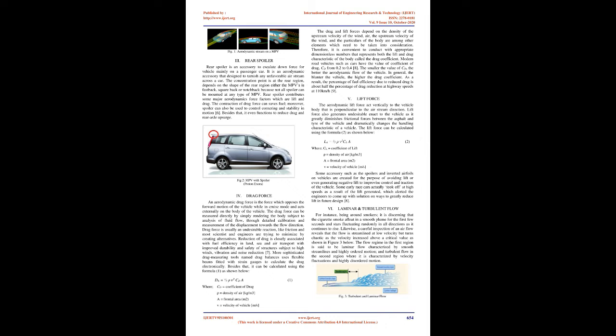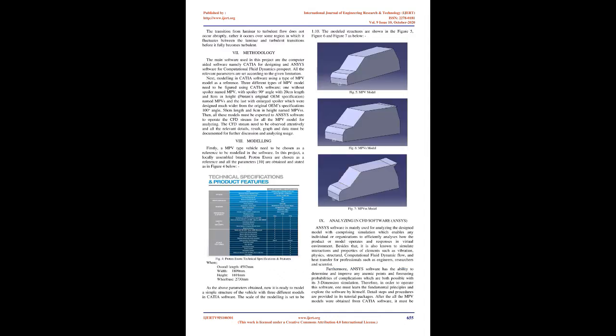4. Drag force. An aerodynamic drag force is the force which opposes the forward motion of the vehicle while in cruise mode and acts externally on the body of the vehicle. The drag force can be measured directly by simply subjecting the body to analysis of fluid flow, through detailed calibration and measurement of the displacement towards the flow direction. Drag force is usually an undesirable reaction, like friction, and most scientists and engineers are trying to minimize it by creating alternatives. Reduction of drag is closely associated with fuel efficiency in land, sea, and air transport, with improved durability and safety of structures subject to high winds, vibration and noise reduction.